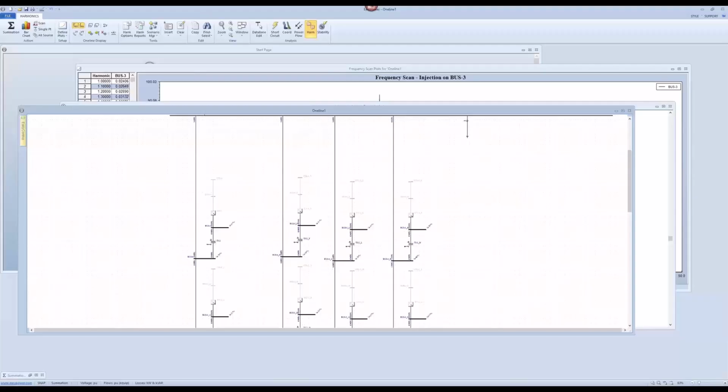If I have 5 inverters, each 2 MVA, to get 10 MVA conversion, versus 2 inverters, each 5 MVA, both meeting IEEE 519, does a smaller number of inverters get you better results? Do the study. I cannot say. It depends.